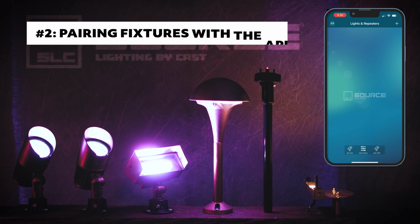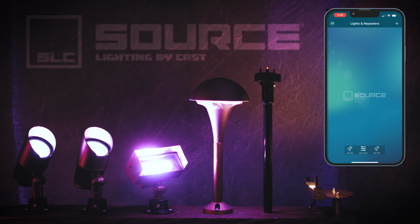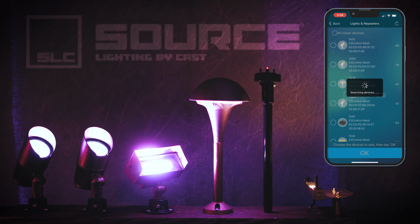Section 2. Pairing fixtures with the app. With the app already open, click the plus sign on your screen's top right-hand corner. Tap the box that says Adding Devices. Next, only turn on the lights you want in this pairing. Once confirmed, hit Yes or OK. Your app should search for the lights.